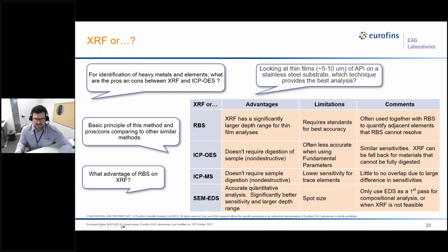Lastly, when considering SEM EDS, which many companies might have access to in-house already, in our opinion, it should only be considered a last resort for compositional analysis, as with XRF, it's just much better quantification accuracy when we consider the significantly better sensitivity and larger depth of range.